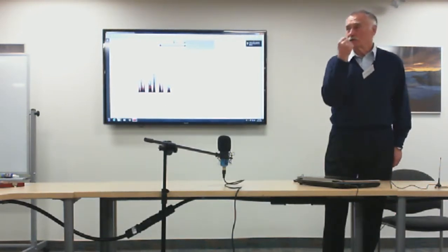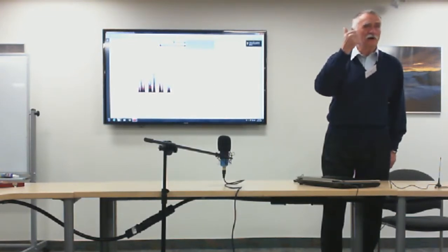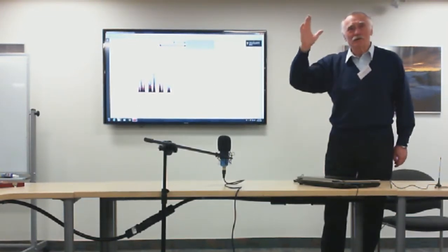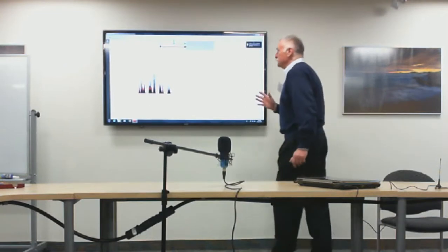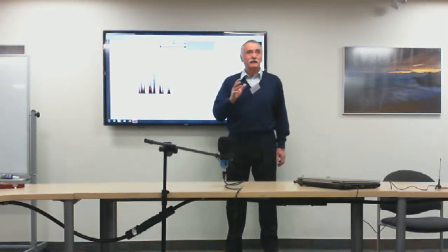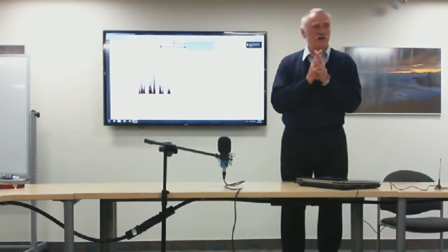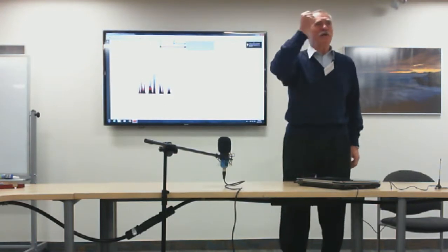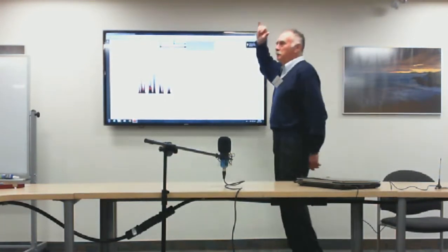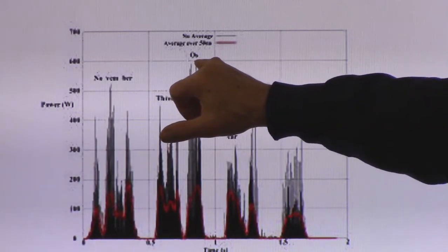As we talk to the microphone, power goes up if you speak up loud, power goes down, and power goes out totally in between syllables and in between words. So what Industry Canada says is that for a split fraction of a millisecond, when you speak up at the peak of your voice, the peak power can jump up to 560 watts.